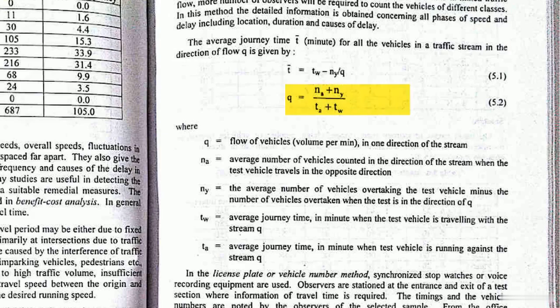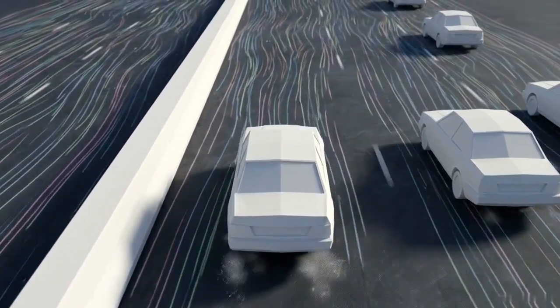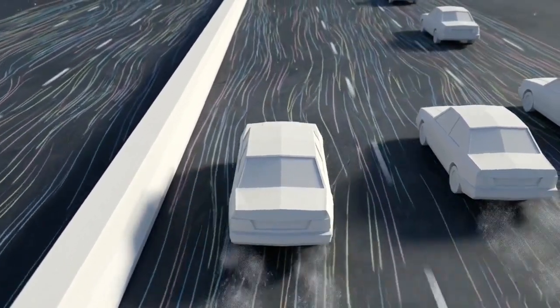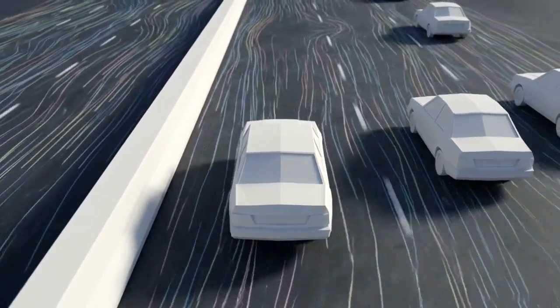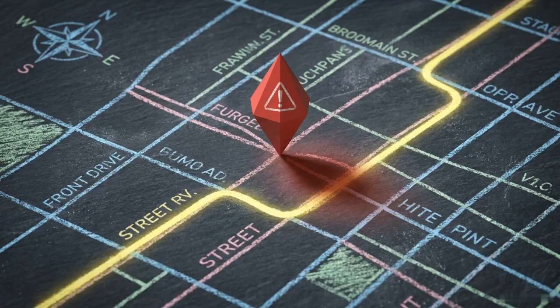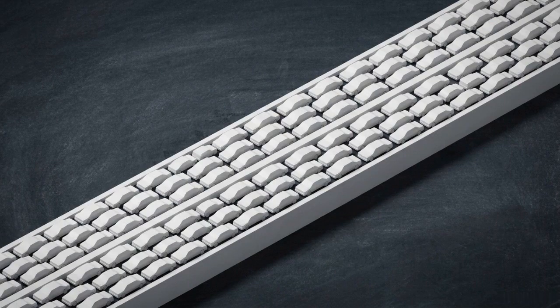By plugging these counts and times into these specific formulas, engineers can solve for the total traffic flow, or Q. This allows us to calculate the absolute volume of a roadway by simply observing relative motion from inside a moving car. The floating car method transforms the test vehicle into an active probe, pinpointing the exact duration and location of operational delays. While volume measures the current rate of flow, traffic capacity represents the absolute maximum number of vehicles a road can accommodate.